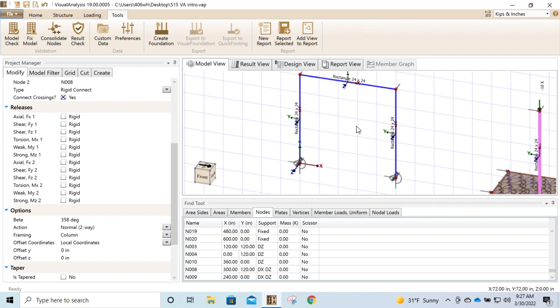So why do you have a footing one? Because with the footing one, I was saying, what if I wanted to design the bearing pressure underneath this footing for the axial forces in a building that has gravity columns in it. So no transverse loads, just vertical loads. What it allows me to do is take into account the fact that the soil has stiffness to it. It has a K. You guys remember soils? Do you remember K factor? Pounds per cubic inch. It's this guy right here.